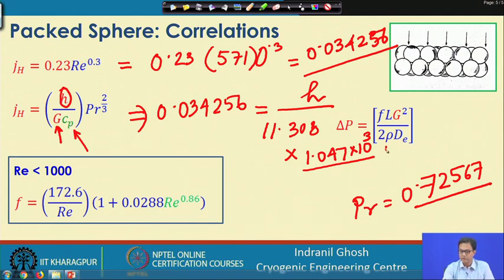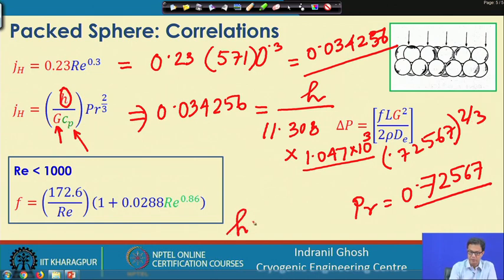So, we put that Prandtl number here, 0.72567 to the power 2/3, and accordingly we find that the heat transfer coefficient comes out to be 502.7 watt per meter square Kelvin.